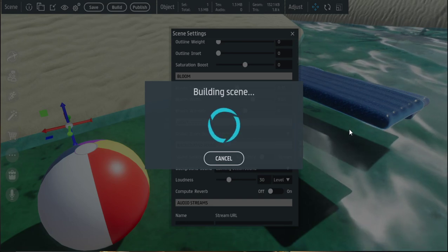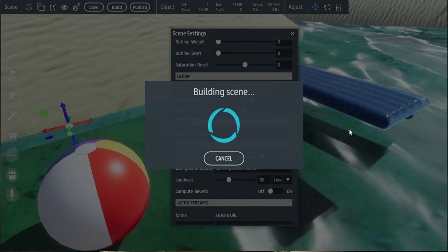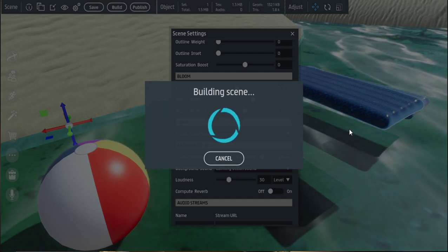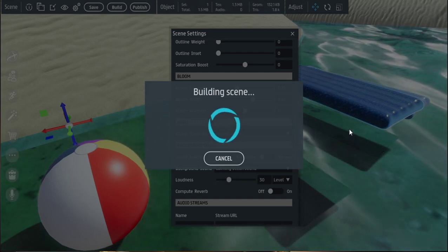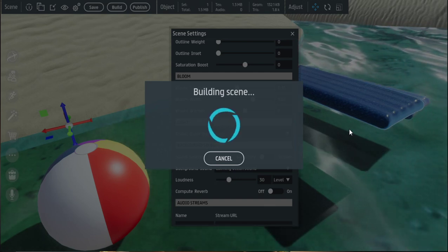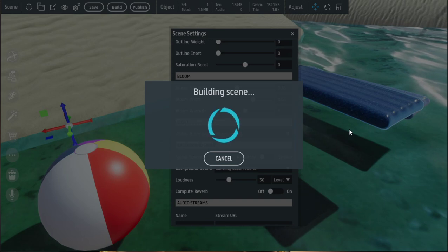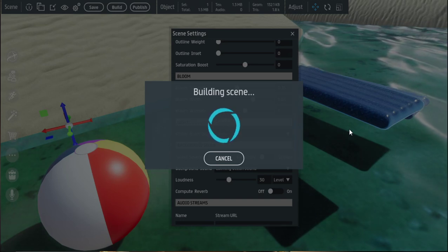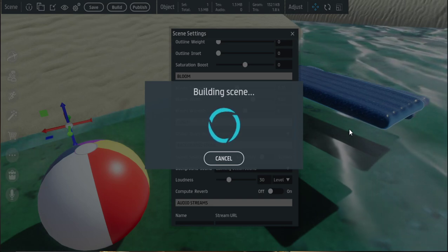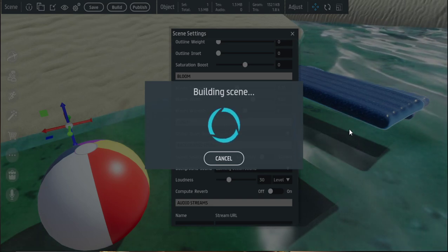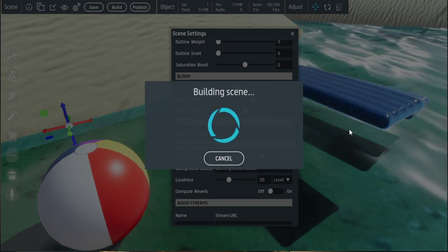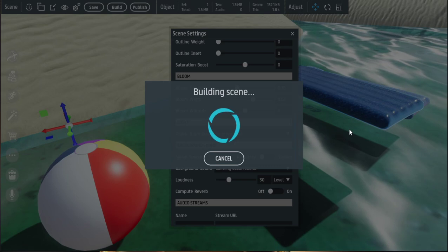Having a totally invisible wall right there, it's basically adding the object there. I believe you can just add a collision right there without even having the object. So we'll go ahead and test that out. I've accidentally done that a few times because of taking tables out. Sometimes when you bring a table in and it has its collision, and then you remove the table, the collision stays there. So a collision will work if you just want it to be invisible and the person won't be able to get past.